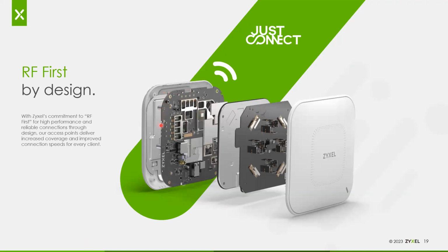So one of the things you'll see is on our access point here, if you pick it up and hold it in your hand and you hold one of our competitors, even one of our more expensive competitors, you will notice ours weighs more. So why is that? We've got a large metal shield that goes behind the PCBA. So this acts as a heat sink, drawing heat off the board and venting it out of vent holes in the top of the access point.